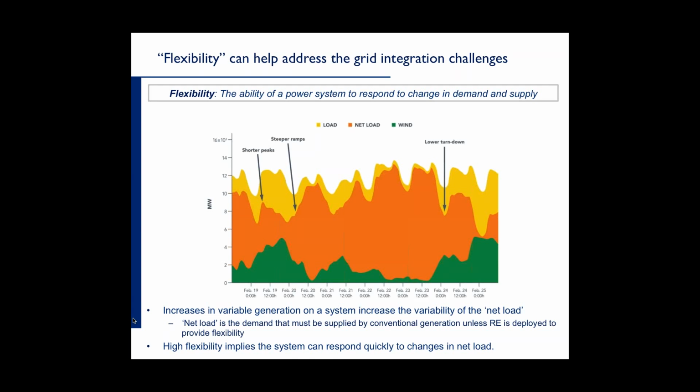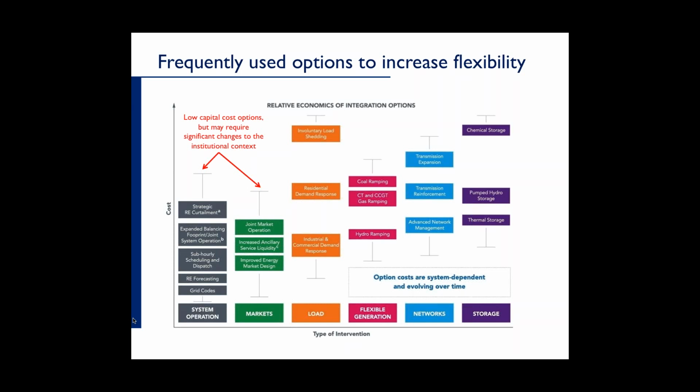So that means that if I have a lot of coal units or gas units, in order to take advantage of all this wind energy, I need to be able to reduce the generation from my coal and gas to 5,000 megawatts now, whereas in the past, with no wind, all I had to do is to reduce the generation to about 10,000 megawatts. So these are some of the key challenges with respect to the variability that the power system operator is faced with. And of course, the question is, can we manage this increase in flexibility? And the answer is, well, yes, there's a lot of tools.